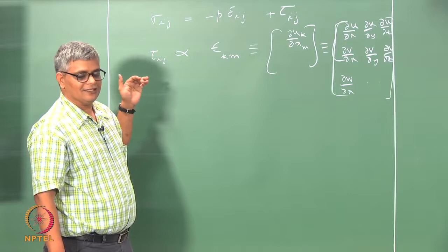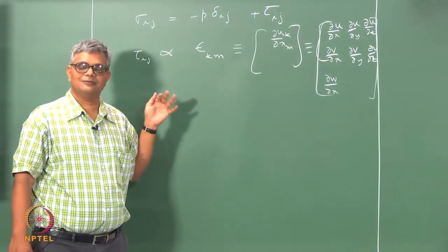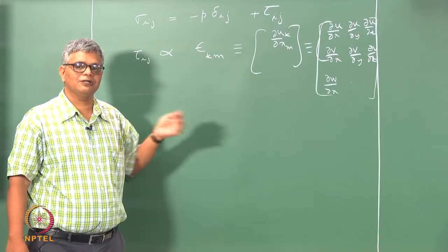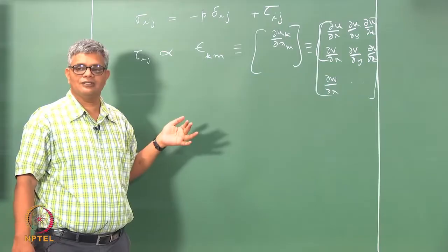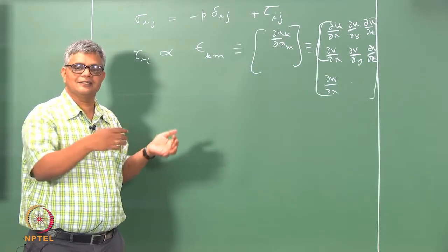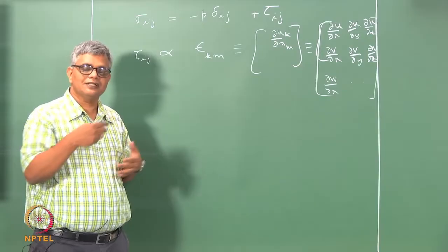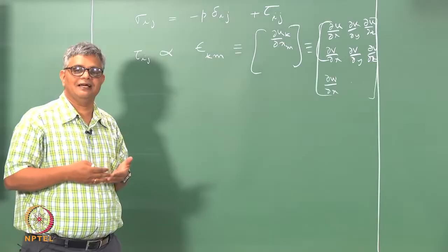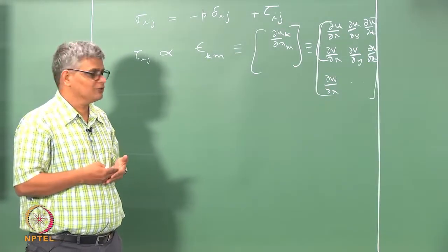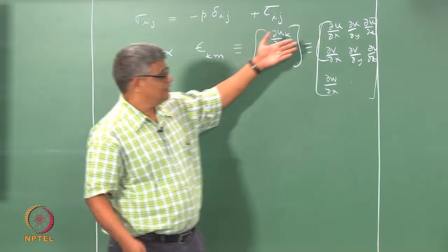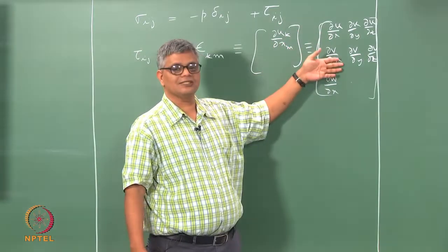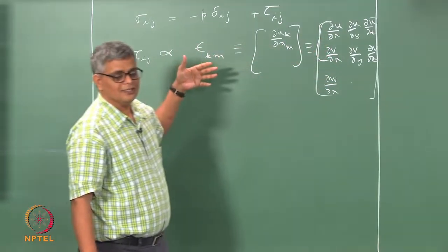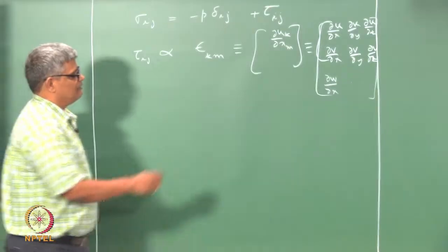We note that the distortion of the rectangular element is possible only when the four corners, the ABCD, have different velocities. If they have the same velocities, then they are just translating in a certain direction without any distortion. When there is relative motion within the fluid element, within the fluid continuum, when ABCD have different velocities, that relative motion is present in the form of non-zero velocity gradient components here, and these give rise to different deformations, like we have mentioned.